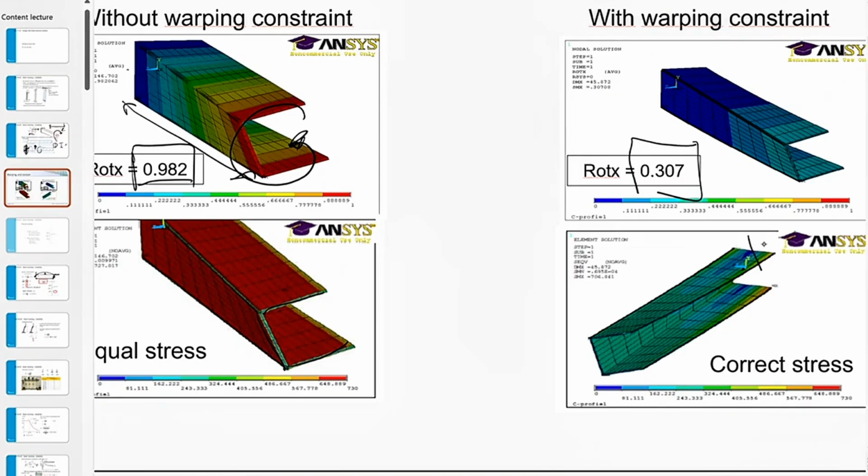Because basically here at the top and at the bottom, you get a plate bending stress, because this plate wants to go in that direction and this one wants to go in that direction, and the single bending over the plate itself results in a much stiffer constraint.